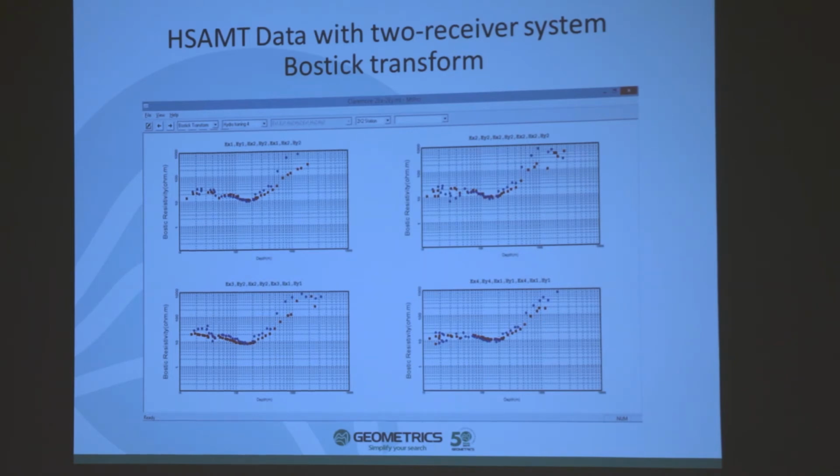And for those of you familiar with borehole logging of resistivity or standard resistivity surveys, these curves are very familiar to you. And because we are making 2 measurements at the same time in each direction, we have along the profile and perpendicular profile, which allows us to get a more accurate view of the true ground resistivity.